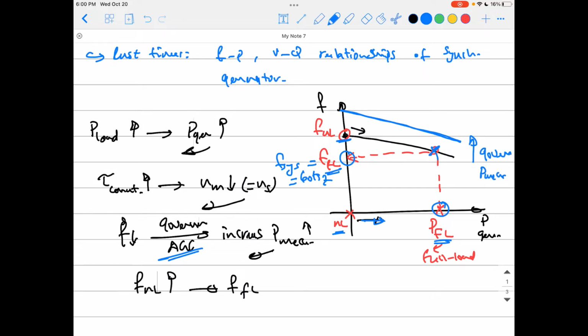So you're now working at a different FP relationship, the blue one, this one. So at the same power here, now we're working at this point. Taking this point back here will give you the same frequency we were working on before. So it's still pushing the same power, the full load power, but at a higher frequency. And this is all the action of your governor here.